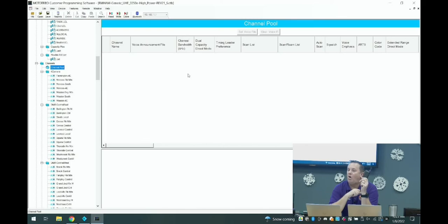We take all of the channels, all of the UHF channels, for example, and put them in the channel pool. There is not a 99 channel limit in the channel pool. They will all fit there. Then we use one of our 99 channels to create a roam channel. And we create a roam group and a single channel, and it will roam.